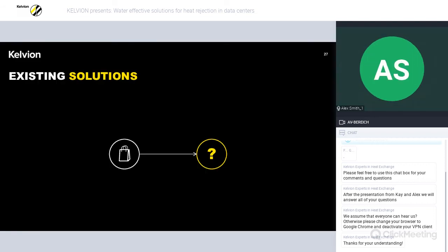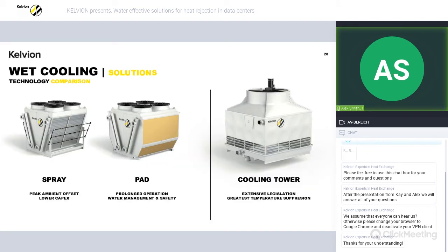Thanks, Guy. So, what are the technological benefits and drawbacks of existing wet solutions on the market today? I will be discussing these three predominant solutions, though others and similar do exist. As a brief overview, spray systems are typically used for low numbers of operating hours, such as in Trondheim, where we only needed a few hours in the year to boost our free cooling potential. Pad systems, however, are designed for operating wet for very long periods of time, or for situations where wastewater needs to be captured and handled.